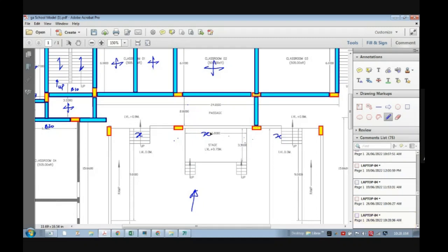But as I said, this x distance which I discussed will not be the same here and here, and the symmetric view may get disturbed. And if the view is getting disturbed, and if it is a really dominant part of the planning, if this is really important from the architectural point of view, where he cannot compromise, then you cannot provide such a column position, then you need to shift it.